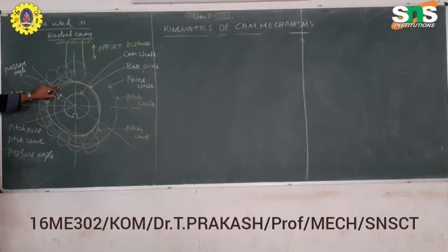This will be the maximum pressure angle. We should not exceed the maximum pressure angle, otherwise the follower will get into a jammed condition. Therefore, we should not exceed this maximum pressure angle for the cam mechanism. This is our maximum pressure angle.